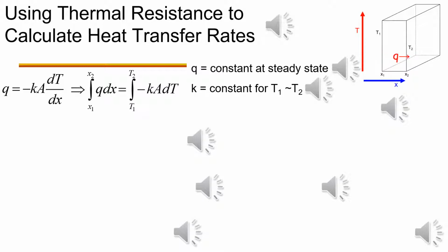At x1, the heat transfer area will be the big surface turned away from you, and is equal to breadth times height. Even at x2, the heat transfer area, here turned towards you, is also B times H. The heat transfer area remains B times H at any position between x1 and x2. Of course, you will be neglecting the slight increase in area at x1 due to the higher temperature, which may cause the solid to expand a little bit. However, chemical engineers, in general, try to make things easy by making simplifying assumptions.